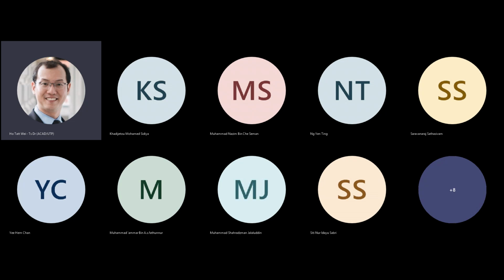So I can actually put an inversion here, an inversion here, an inversion here, an inversion here, and that would make it equivalent. So let me delete this first. For some reason, this thing is always coming up today. Very annoying. Okay. And the reason I'm putting in this inversion is because this now becomes equivalent to a two-stage NAND gate.